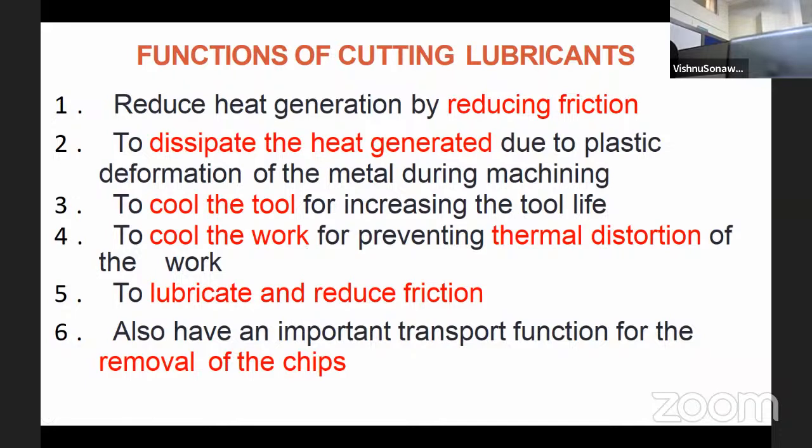To maintain the temperature of the work during machining, the proper lubricant must be supplied to lubricate the part and reduce friction, and it has the important transport function of removing the chips and cleaning the machining space.